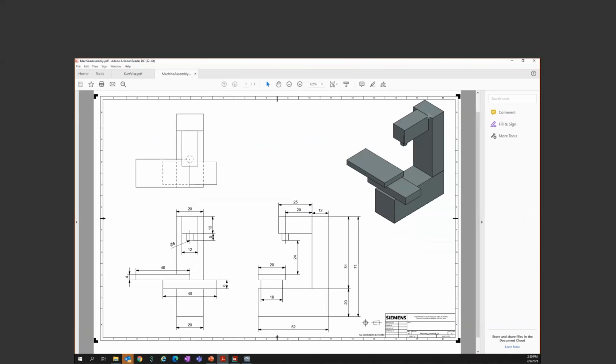All of this stuff rides on a Z axis. Separately to the Z, I have a saddle that is driven by the Y. On top of the Y-axis in the saddle, I have an X-axis, a physical ball screw, and that's driving my table. This is the kinematics. So what we need to do is describe this to the machine, to the controller. So we're going to do that by creating some simple offsets and then laying in our axes and building up our machine. So that's what we're going to start to do first.